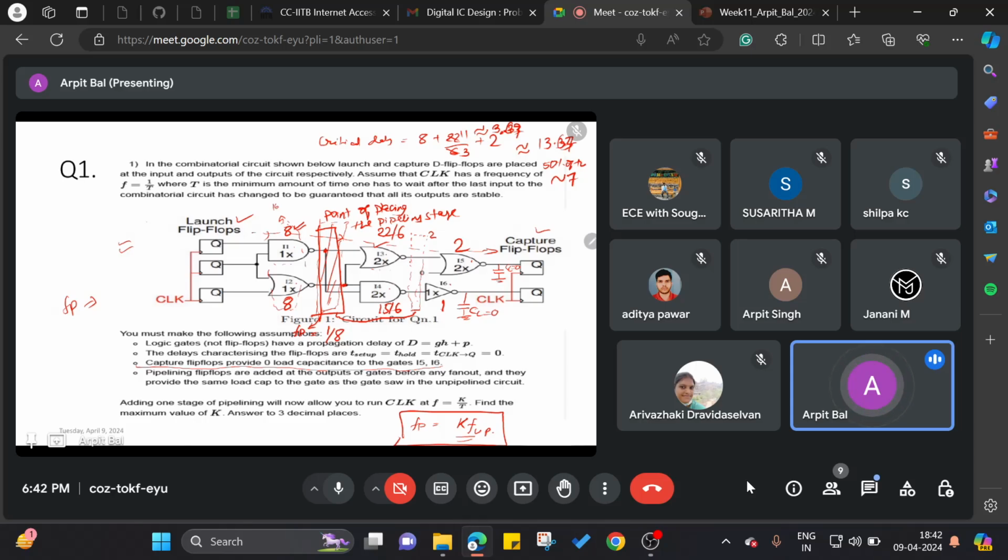Whatever I do, I need to ensure that the data is correctly available to all the blocks. I can't violate that condition. Even if I place a second pipeline block, I need to wait for the data to arrive till this pipeline block ends. Because of this, the second pipeline block's clock can't be made faster than the first pipeline block's clock.